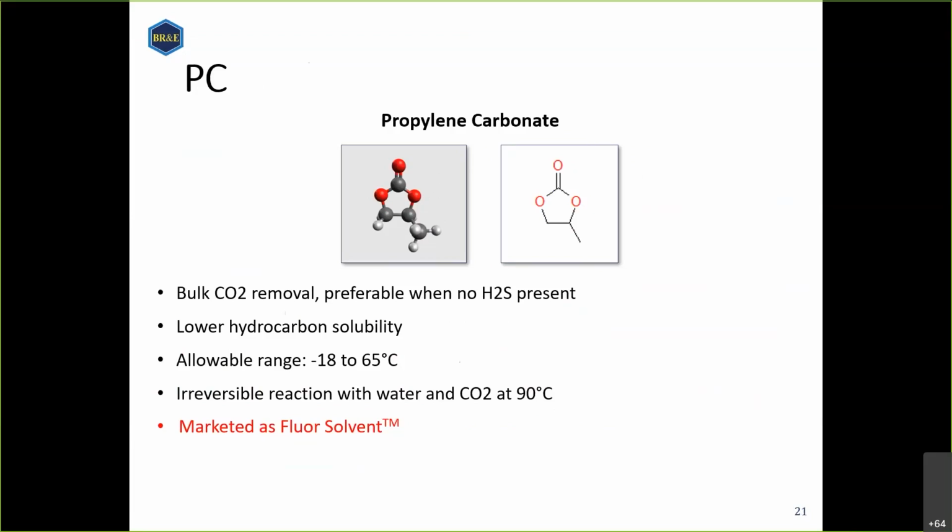And then finally, we've got propylene carbonate. Propylene carbonate is very good for bulk CO2 removal, preferably when there's no H2S present. And this is marketed by Fluor.